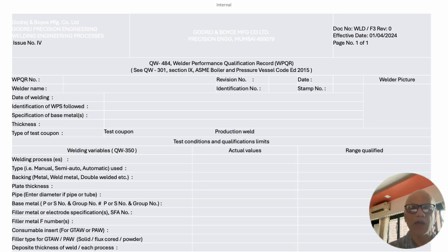Different nozzles have reinforcement pads, and you have a flange on the nozzle, so that flange may be obstructing his accessibility, view, and access for the torch. The position which he is going to weld may be 1 meter high, 3 meters high, 10 meters high, or it could be a very large bridge, tower, or column where he has to make himself comfortable, even though it is going to be the most preferred position of welding, 1G or 3G or 2G.